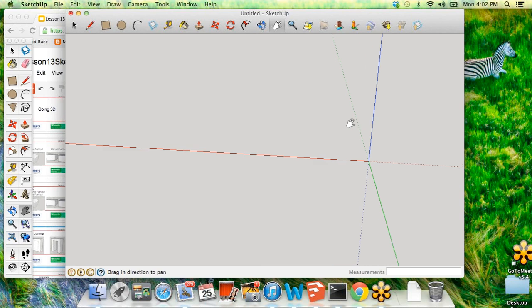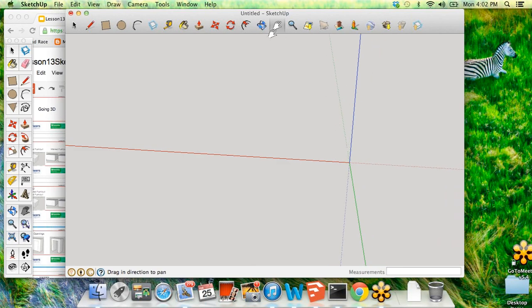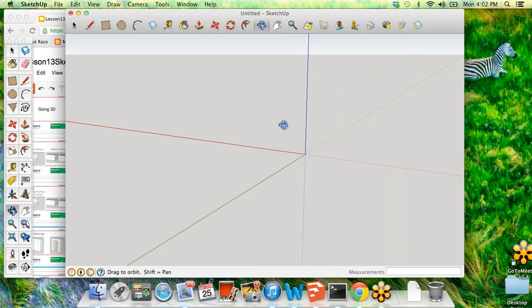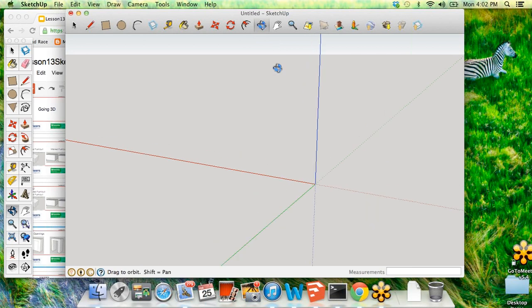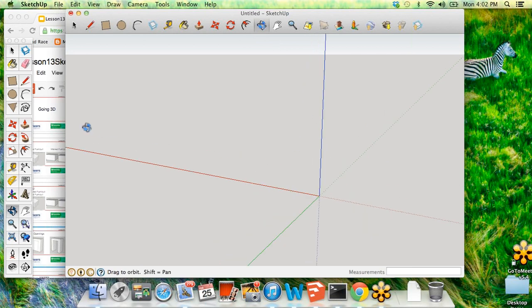In this one, we're going to combine a few ideas. If you could watch me this time, and then I'm going to want everybody to create their own archways as well. I'm going to start by creating a rectangle, and I'm going to create it 4,000 by 1,000. So it's this nice long rectangle, and I'm going to pull it into a box.